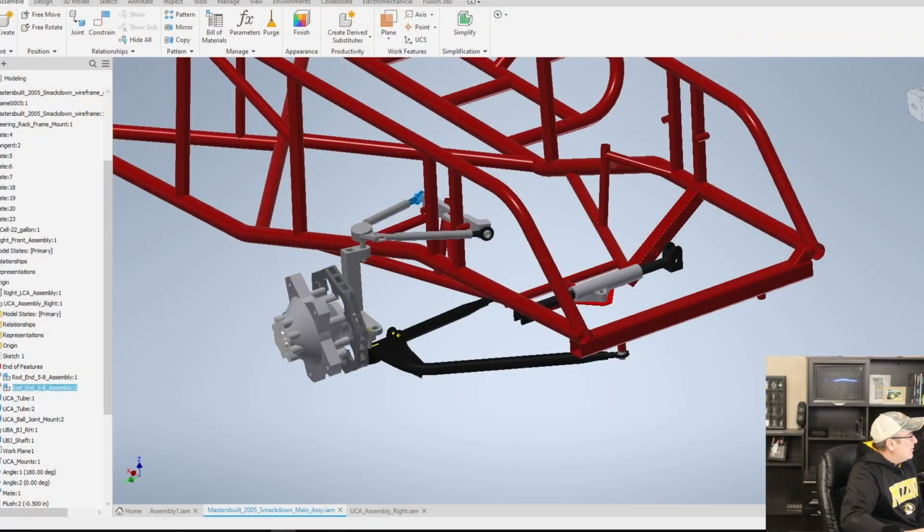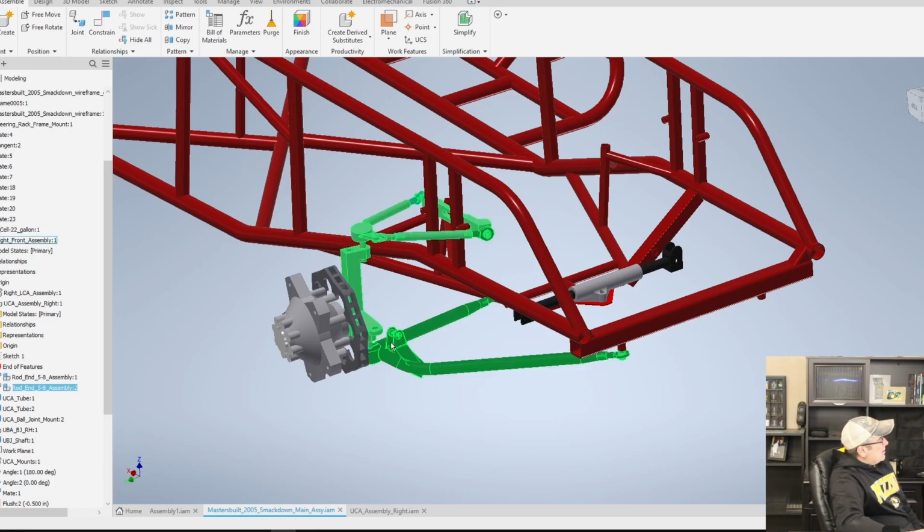But just real quickly, a recap of what we're doing here. If we look at the front end of a race car, we are going to calculate the position of the upper ball joint, the lower ball joint, the outer tie rod, and 2 points along the spindle axis. So we have those 5 points that we're going to calculate, along with the lower shock position.